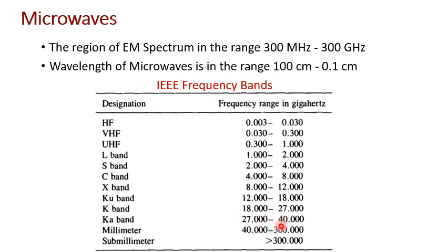Now, all the frequencies above 40 gigahertz are known as the millimeter waves. We know that the spectrum up to 30 gigahertz is highly congested and used up. So, millimeter waves are considered the solution for the next generation of wireless communication, or 5G. As you go to higher frequencies, the size of the antenna that can be used becomes smaller. At the same time, the data rates can be much higher, up to 10 gigabits per second in the millimeter waves.